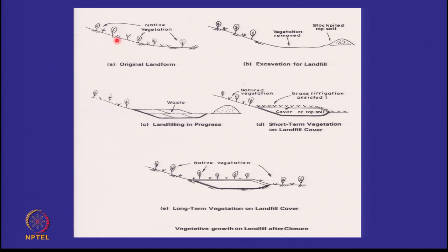We also recognized that making a landfill did not mean burying the waste, but it meant that we are preparing a site to receive the waste. We have to bring the land back to its original form. It may be a little raised ground, but the same vegetation should come back at the top of the landfill. And over a period of time, this waste should stabilize, and then only it can be considered to be permanently stored. If it is not going to stabilize, say after 100 years, which is the design life of a landfill, 50 to 100 years, then it is only temporarily stored.